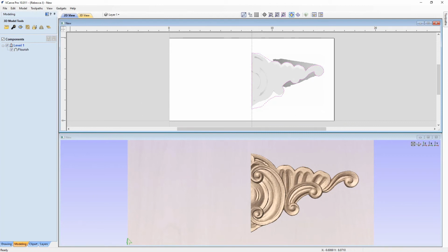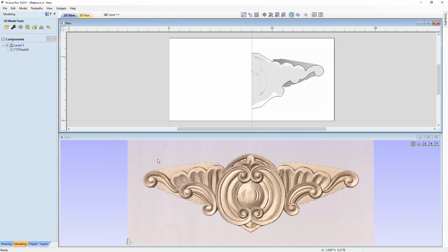So what we could do is just go to Edit, and we're going to undo Close Vector, and then we're going to take that vector. First off, we'll just go into the clipping mode and we're just going to undraw that. Okay, so put it back so we don't have any clipping involved at all. We've just got the mirror mode applied.